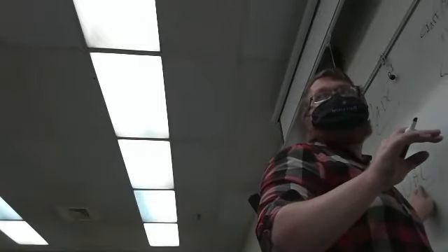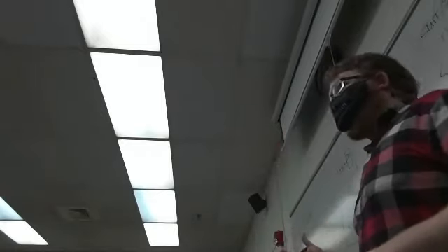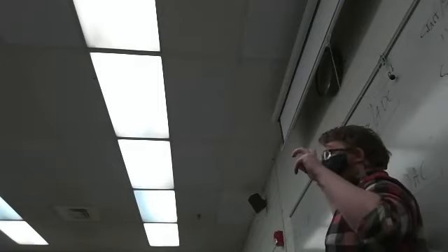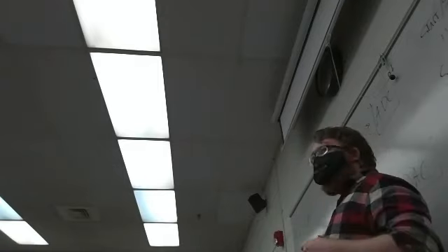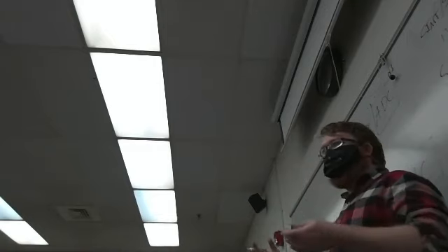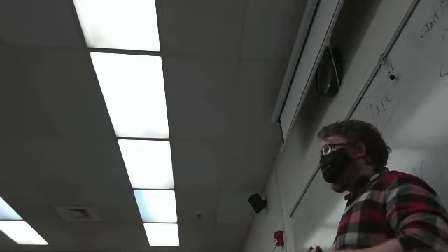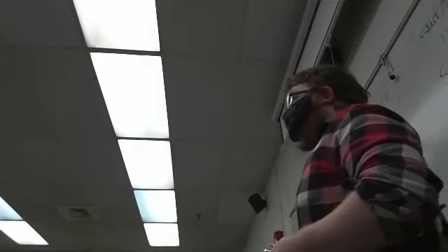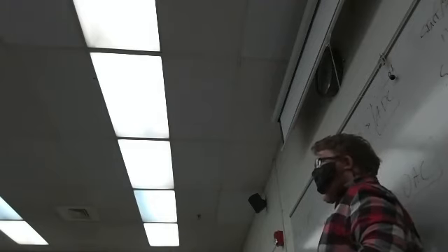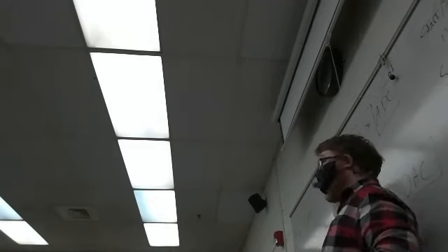Wait, set input as the switches or the DAC? Well, it depends. I have to finish writing the lab to figure out what it is. We can do two different things with the switches. We can use the switches to set the DAC level, or we can use switches to generate data. You may need to be able to do both because it's a useful debug tool to figure out what's going wrong. Then I can test if the ADC is broken if I can set some switches and get the values out that I expect.